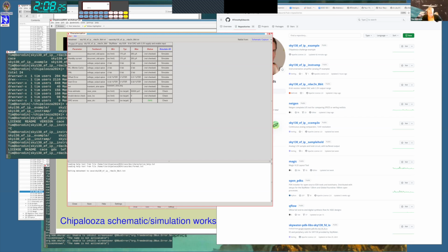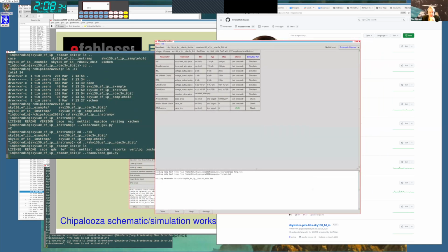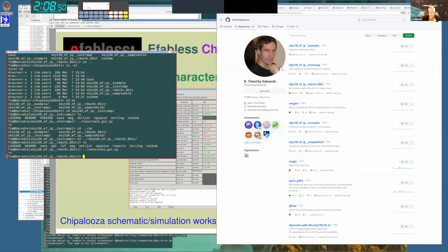Christopher Meyer asks, how do you simulate mismatch in the CASE environment, assuming this probably requires Monte Carlo? Well, in the SkyWater PDK, they define, or I should say I define because I created the .lib file, separate corner cases for mismatch. So where I was specifying in my file what was being simulated at typical, fast, or slow, I can simulate at typical underscore MM or fast underscore MM.